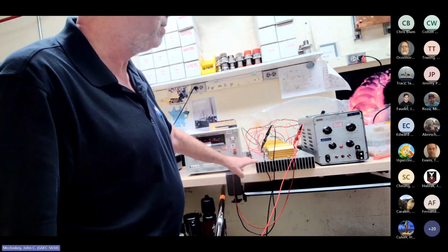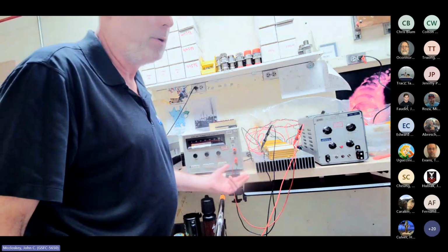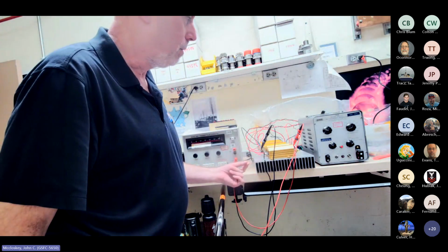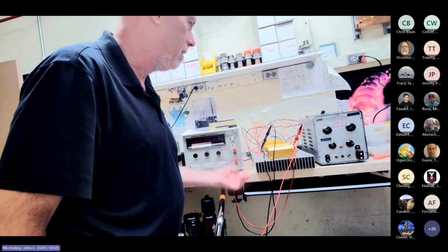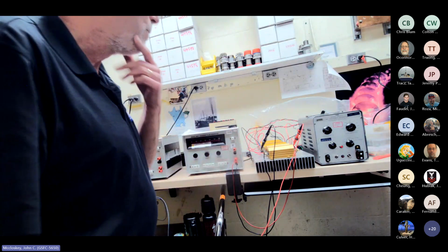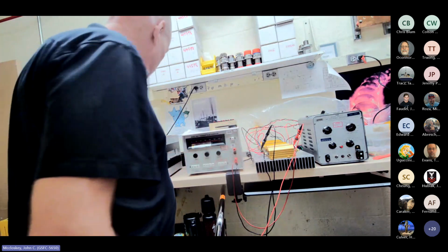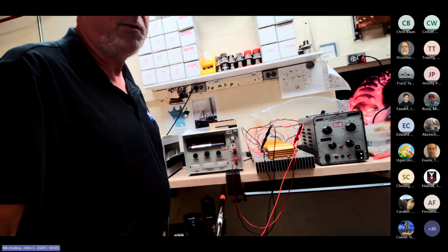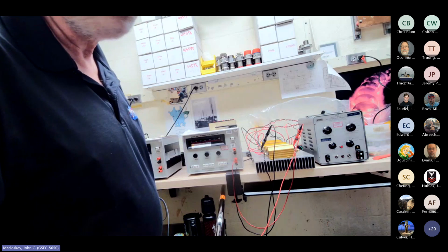It's much more important with CS101 because when you're going into a half an ohm, you're putting a fair amount of current in there, and that's more steady state. So the resistor is going to get hotter more than likely with CS101. But even still, when you're putting 30 volts or more across, or if you actually go with some of those defaults and you're putting 200 volts across a 5 ohm resistor, you want it to be able to dissipate a fair amount of power.